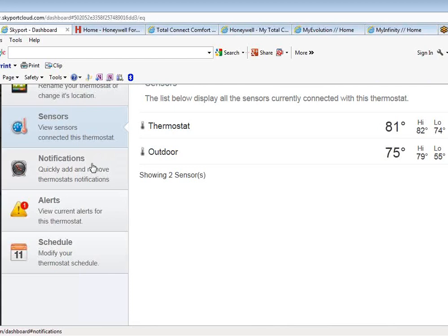More asks, what is the fan related to, the HVAC supply fan? Correct. The fan is the fan for the furnace or the rooftop unit or whatever the HVAC equipment is that you're controlling with your heating and cooling. Bob asks if the outdoor air temperature sensor is wired, and the answer to that is yes. It's the same as that remote room sensor we were talking about earlier. Traditionally, it is wired. The one Benstar can supply is a wired stat. We do occasionally use third-party versions to get wireless ones, but it is fairly costly to get the wireless ones.